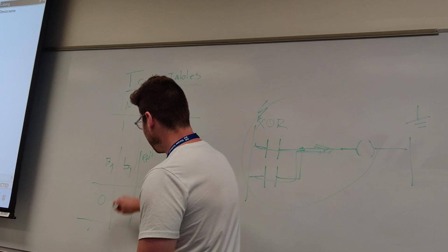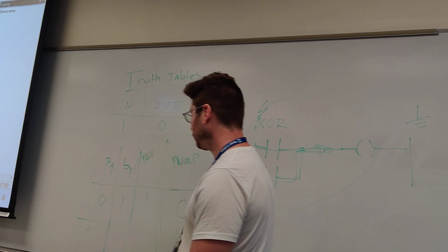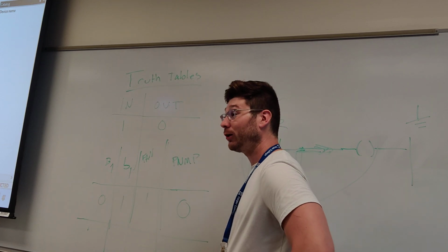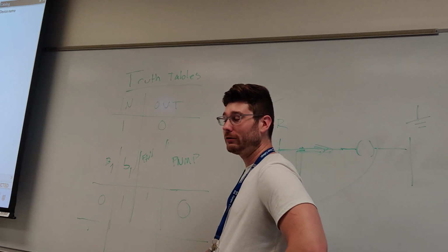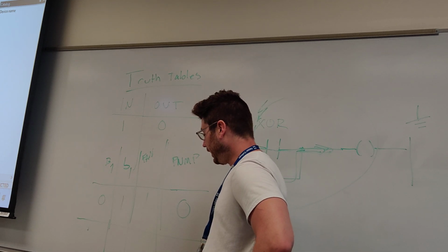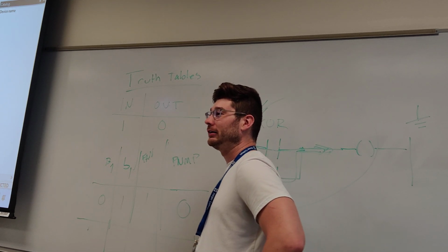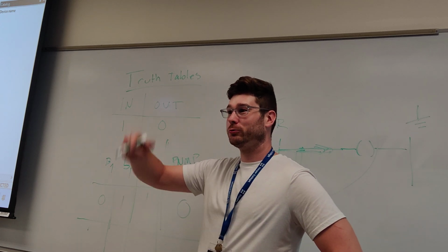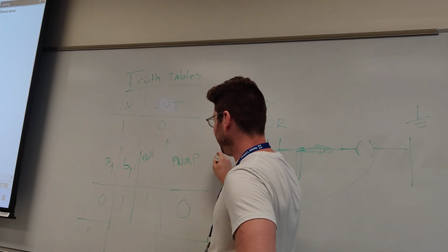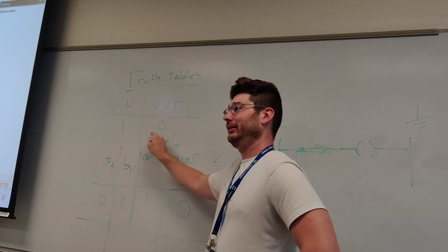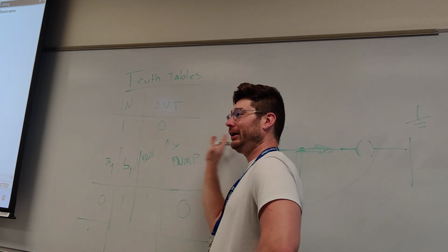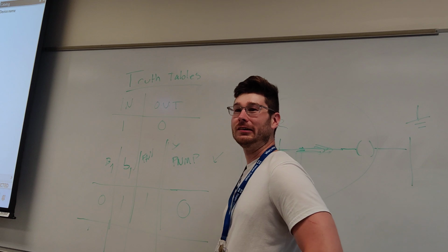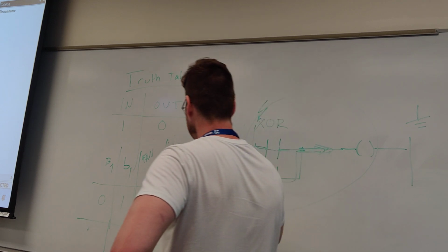This comes up in a later exercise when we're going to simulate making a car wash. For example, we have wash settings. If they ask for a deluxe wash, if the deluxe wash switch is up, you want to run the fan and the soap and the heater. If they don't pay for that, you run other things. This is the essence of the truth table.